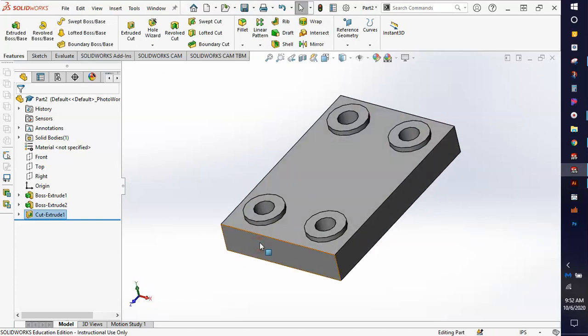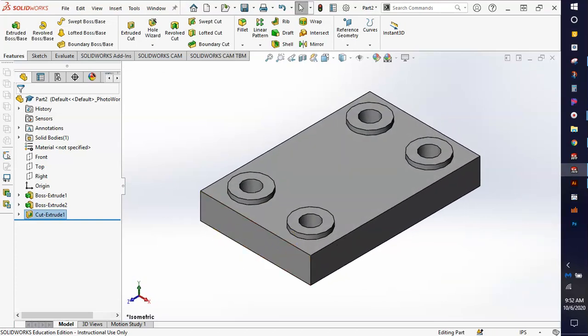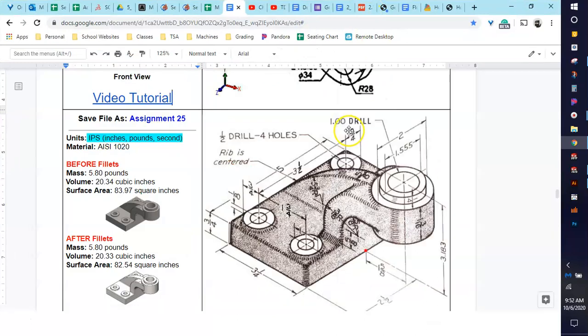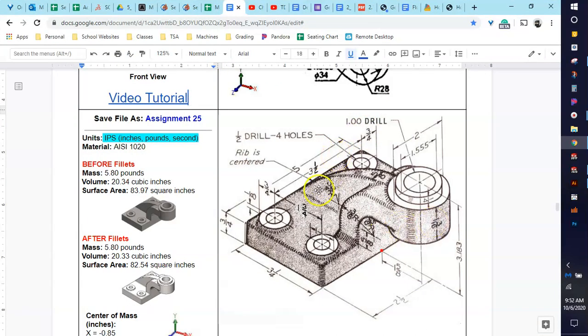Now to do that middle part. The middle part here shows 2 different things. It shows a rib, which we'll do later on. That's like a support piece. And it shows this kind of curved arm that comes out that holds this cylinder. So we're going to do this arm portion first because we don't really know where the rib goes until we do this. And we also can't really draw the cylinder unless we make a whole bunch of planes until we have this arm because that's connected to it.